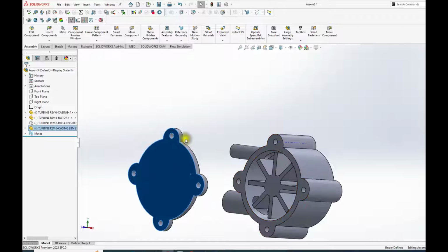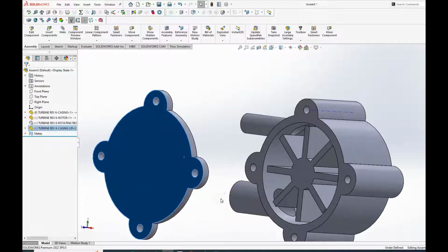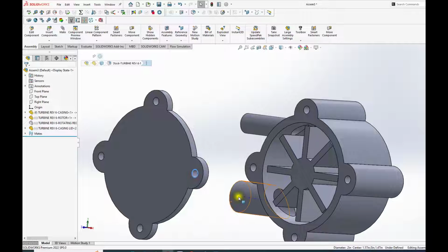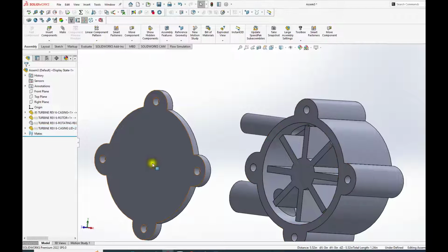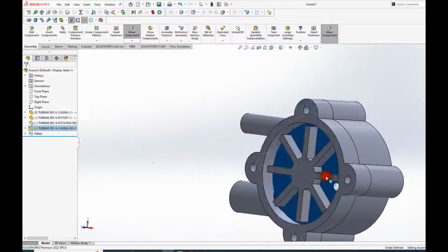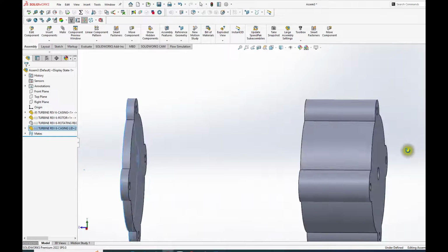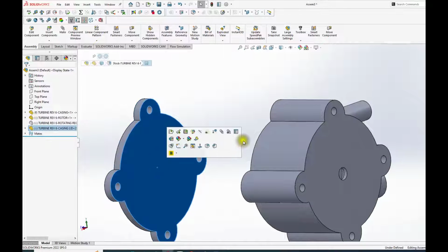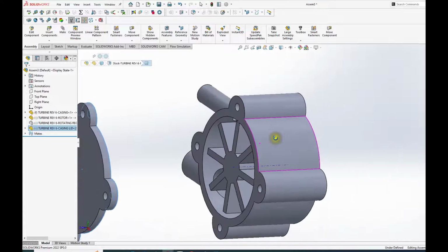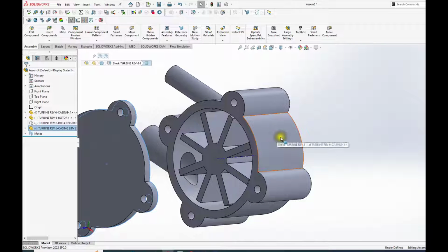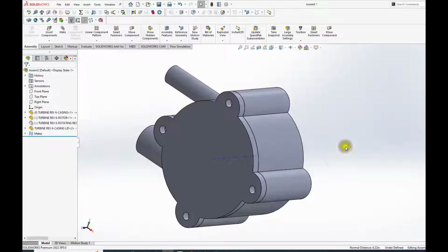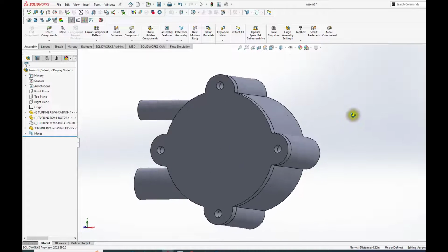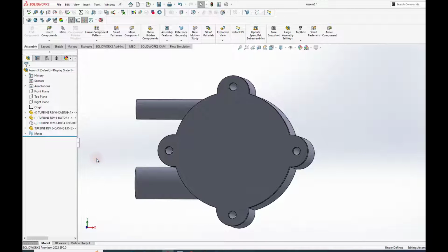So obviously you can move it because you're only matching. It's like you put a bolt here through here, and this will move. Now to fix it in space, just that guy and this guy, concentric as well. Now it's fixed in space. It can move back and forth, but that's it. See, now the only thing missing is that definitely you want that guy and this surface. You hit control and this surface touching, and you're done. So now you got your full build in assembling your turbine.